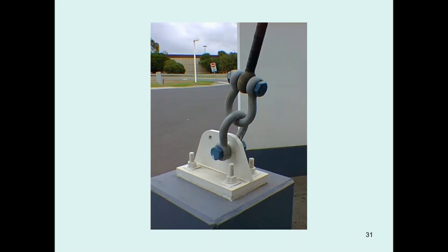If not, the eccentricity will produce extra stress, and the result is going to be lower than the actual one. We also want you to understand how the types of specimens are set, such as steel, where you have to reduce the section. For concrete, the specimen cannot be too tall because it may cause some kind of buckling.